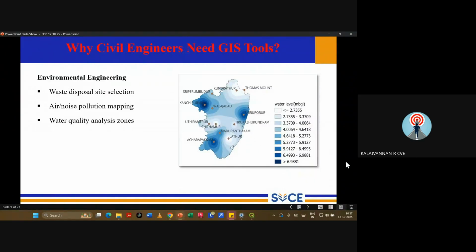We also analyzed the data from post monsoon and pre monsoon, how the groundwater level fluctuation has happened within the given locality, and using that we mapped it. We found that a few locations, like the main part of Kanchipuram, the Tirupurur region, and Acharapakkam, are under major groundwater stress, because people often extract more water considering the drought and insufficient domestic water supply.